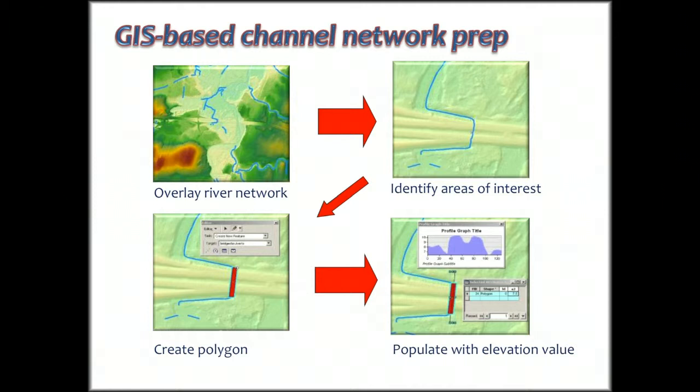Tributaries will be mapped in the wrong location. The topology of that watershed will be incorrect. So we can't just run a standard watershed analysis workflow on a high-resolution LiDAR DEM. That's maybe a bad thing, because that means we've actually got to do a lot more data prep in order to make the DEM work in this procedure.